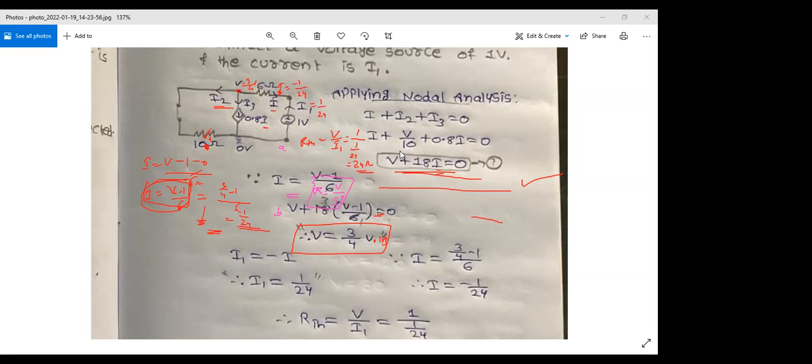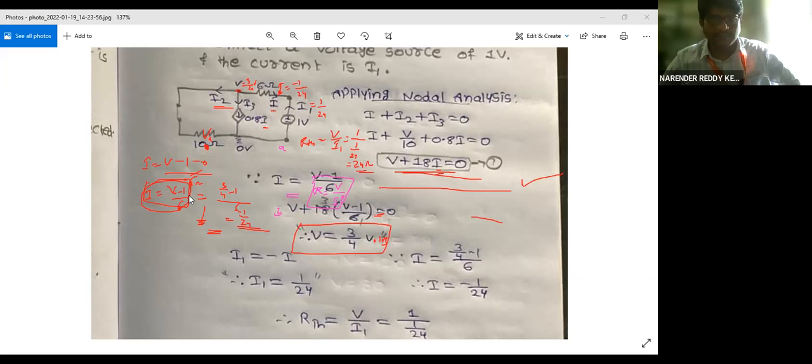is going to change, right? Once the two equations change proportionally, see here, if I take it as V minus 10 here, instead of writing I as V minus 10, when I use a 10 volt source here, it will be the same when I apply here, right? So there is a proportional increase in the current with the change in voltage. When these ratios change proportionally, the value of RTH remains the same.